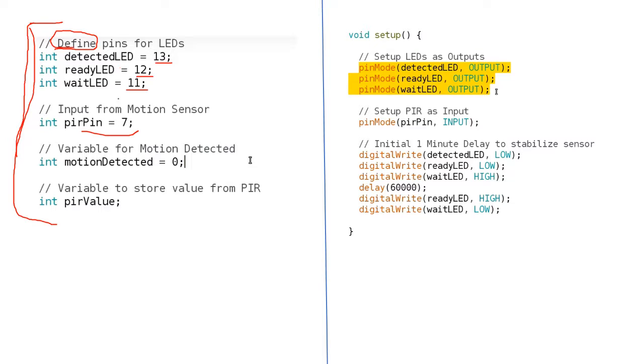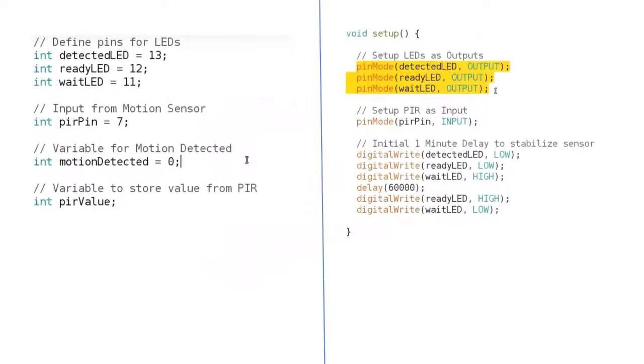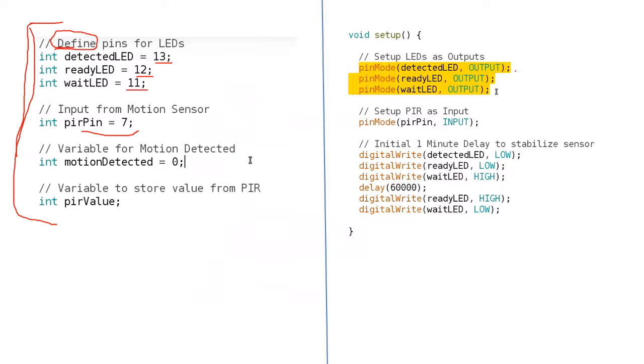Probably it is very necessary, of course, but if you don't understand, again, we'll take you through this in the next session. And I've said now in setting up, this becomes an output. I think all these things we will be able to talk about. So this is actually how the movement sensor works, this is what it uses. And I put a delay of 60,000, like almost 6 seconds to be able to get that working.